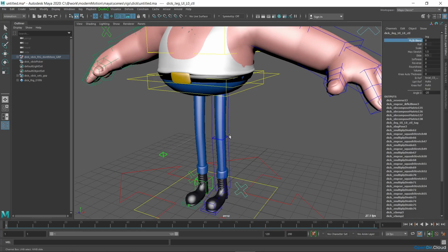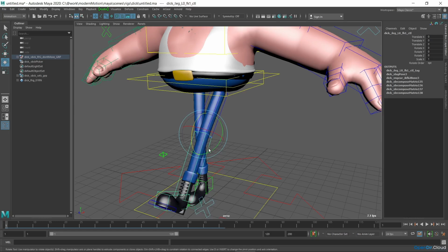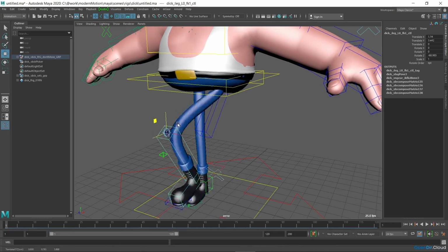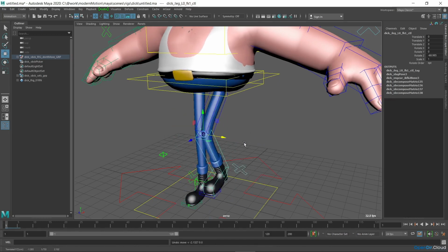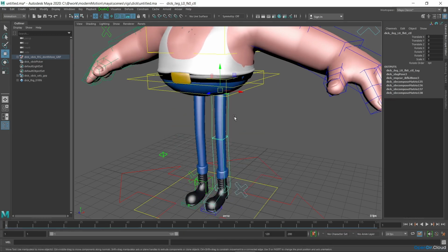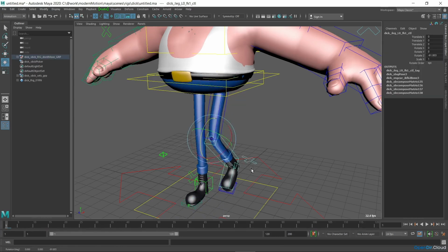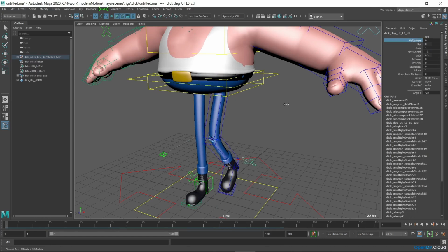Each segment in direct kinematics mode inherits the transformations of its parent. You can rotate the controller as well as move it. As you may have noticed, if the inverse and direct kinematics modes set a different pose, the leg will shift when you switch between modes.